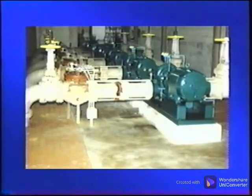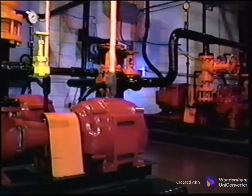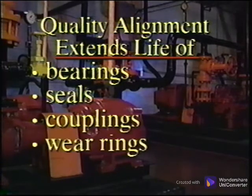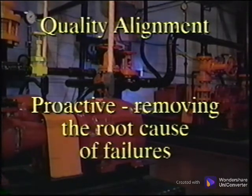Although the coupling may be able to handle these stresses, the mechanical seals, bearings, wear rings, and so forth cannot. The stress created by the misalignment is still passed on to these components, causing premature failure. So it is necessary to be concerned with misalignment. In contrast, a machine in good alignment condition extends the life of the bearings, mechanical seals, the couplings, wear rings, and the shafts, as well as reducing vibration and minimizing shaft bending and cyclic fatigue. Quality alignment is proactive and removes the root cause of failures due to the forces of misalignment.